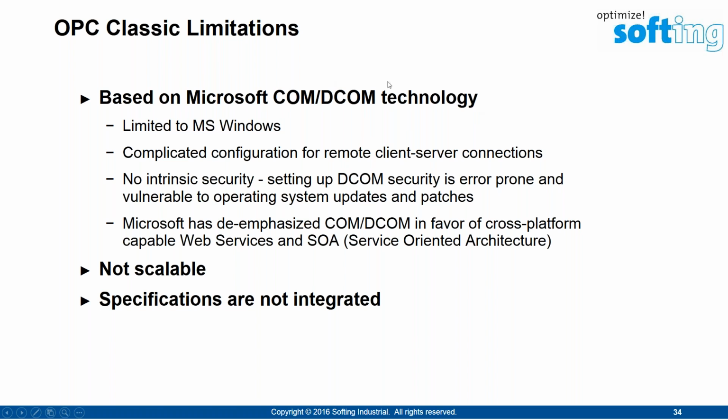Okay, so far I've been talking about the standard now referred to as OPC Classic, which has a few limitations. Like I mentioned at the beginning, it's based on Microsoft COM and DCOM technology, so it's limited to PCs running on Windows operating systems. Also, COM and DCOM can be difficult to configure for remote client-server connections.